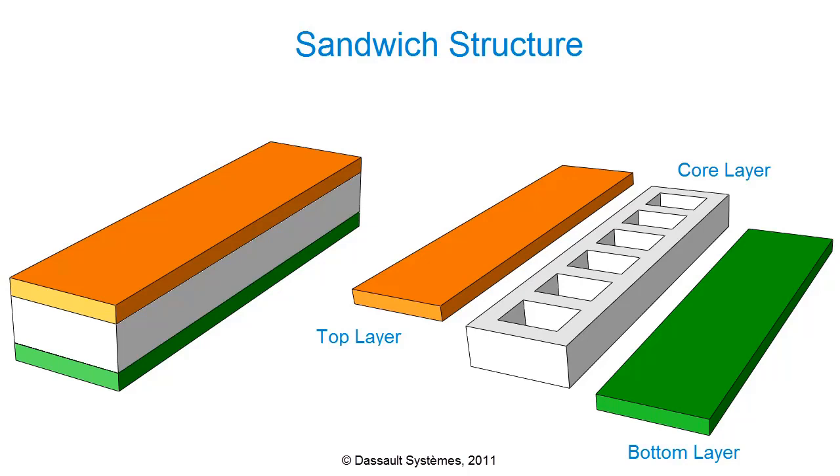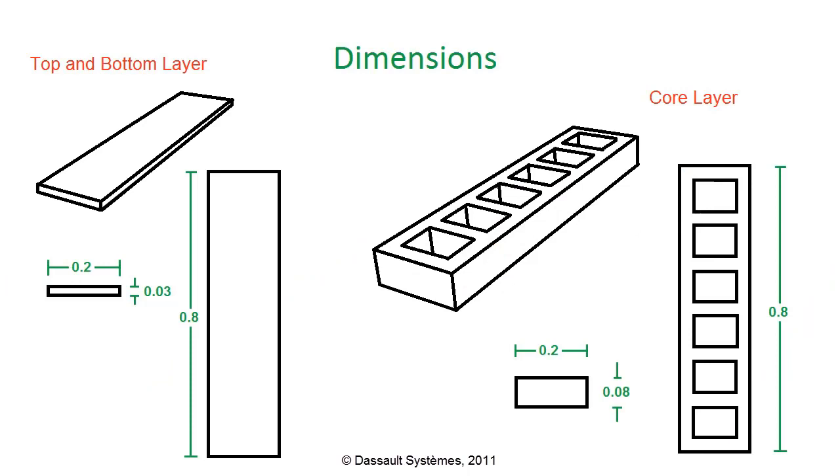The plates of a sandwich structure can be fixed to the core using adhesives, welds, fasteners, or other methods. In this example, we do not wish to model the adhesive, fastener, or weld, just the fact that the surfaces are constrained together. The tie constraint will be ideal for our purposes. The dimensions of the parts are displayed in the figure. They are in SI units with length in meters.